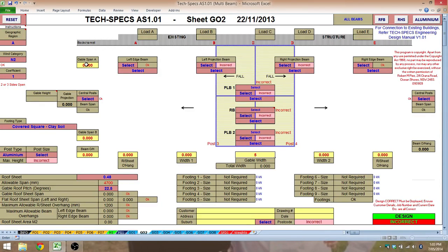So we'll make this a 5 metre by 5 metre gable. We'll put a 500mm overhang on the front. So if we go through, select our ridge beam, which I haven't selected because I've missed it. Select our ridge beam, we'll put a point load beam there, and you'll see it's added posts either side, and we'll select a point load beam for the front.